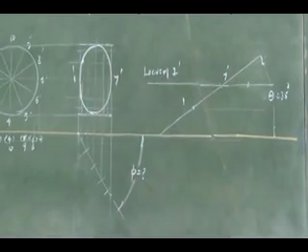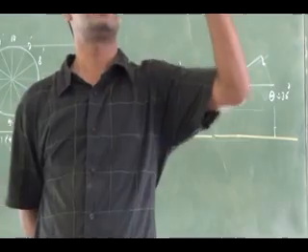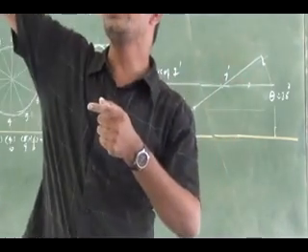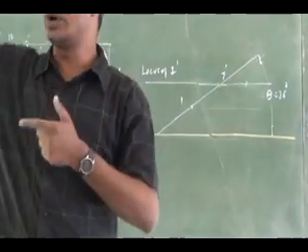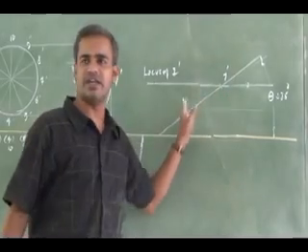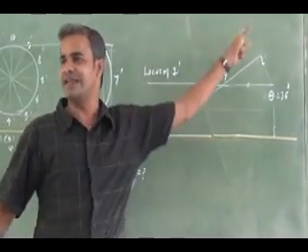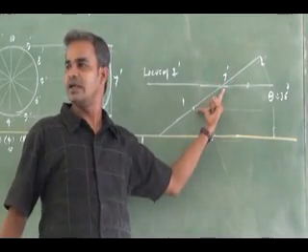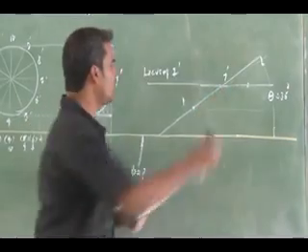So what is wrong I have done here? First of all, what you have to do in your straight line problem? True inclination will be measured with the true length. What is the mistake I have done here? Instead of having the true length on the true inclination line, I have kept the apparent, the top view length. I have marked the wrong one.